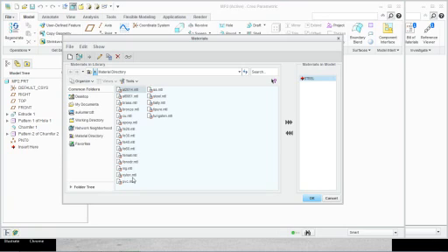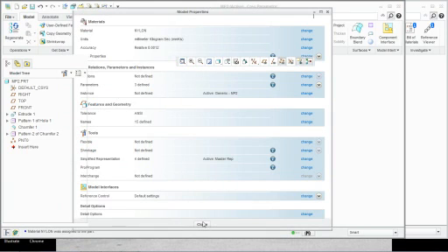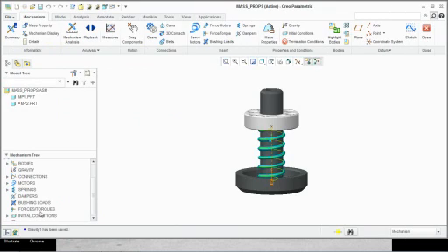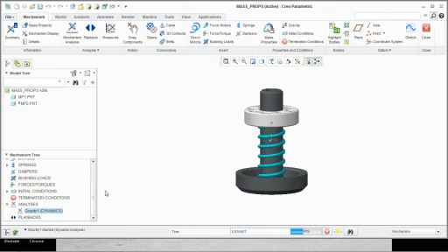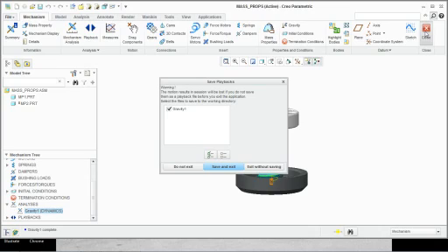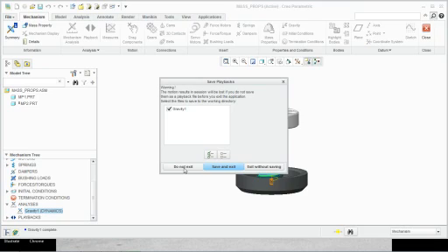So we have nylon as the part material. So you go ahead and rerun the same analysis. So you can see how the part doesn't move as much. Now I want you to also notice that there is no damper applied to the spring, so the spring is being really active, right? In further examples, we'll talk about springs and dampers, and we can see what kind of effect a damper would have on this kind of data. So that's my second example.